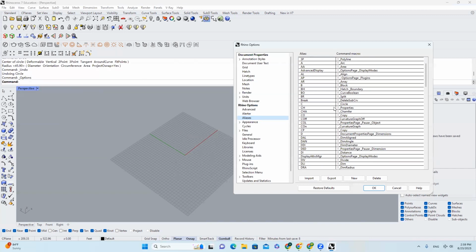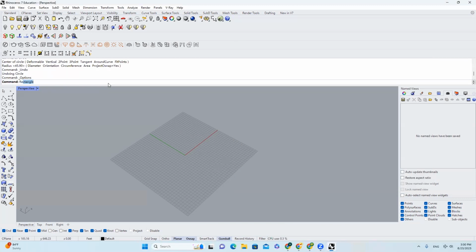How do you import this kind of files to Rhino? I made a separate video in the Rhino basics on my channel. So REC stands for rectangle. I click it. The beauty of the command-based is, for example, if I click 0 right now and type in space, it will start from this origin, and then you can select 3-point or round it, and so on and so forth.